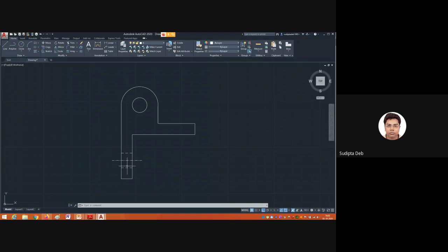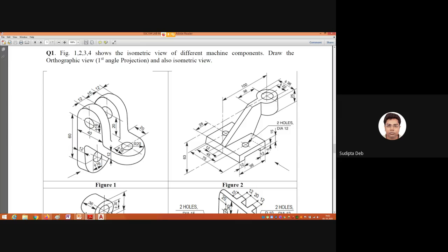Now the same thing I have to draw on this side also, because there is also a hollow section. This is the hollow part I have identified by hidden lines, because up to this it is hollow. Now you just try to understand the figure. This is the hollow section. When you see your front view, on the lower side you will get a rectangle and this side also you are getting a rectangle. You cannot see the round section. Okay, so it will be better if you make it a hidden line at the same time, and here also you have to make it hidden.